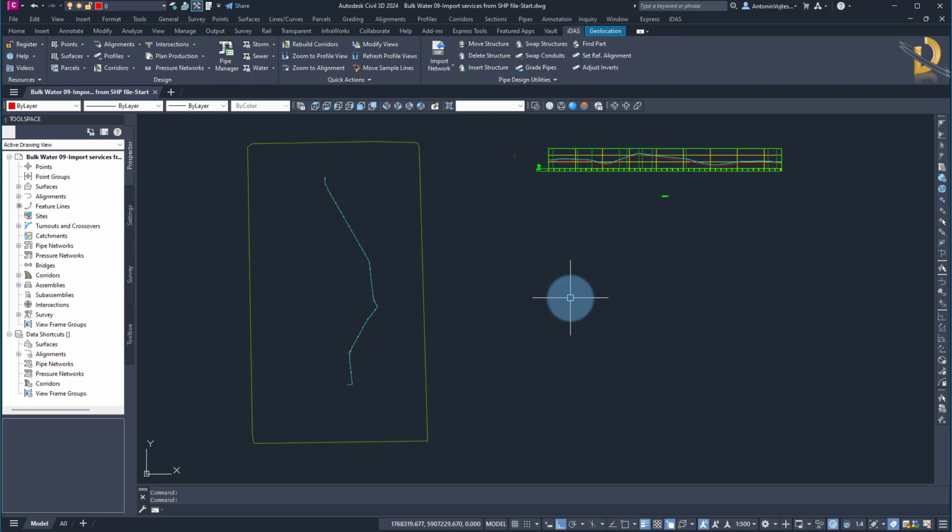And the other important thing is that you might get a shapefile for the entire area and it might contain quite a few hundred parts and structures, and that might make your Civil 3D very slow. So I always suggest pre-process your shapefile. Let's say you can use QGIS, which is freeware software for shapefile editing, and process the data and make sure that only parts that are crossing your design are imported. Otherwise, it might make your Civil 3D drawing very slow, and that's not very nice.